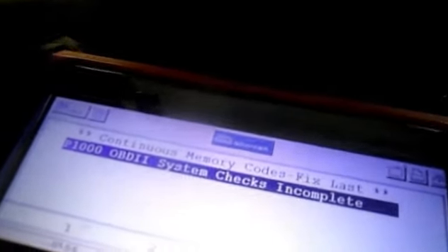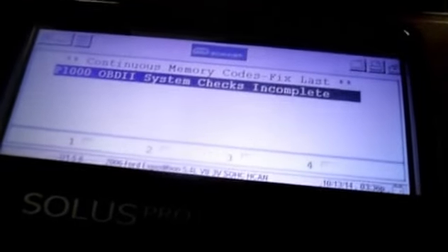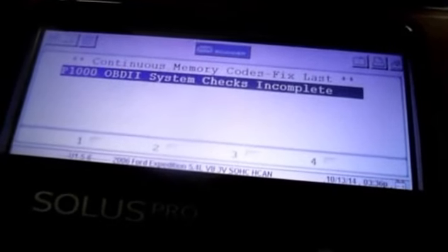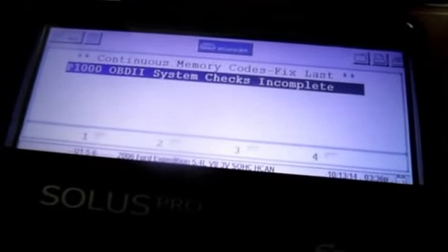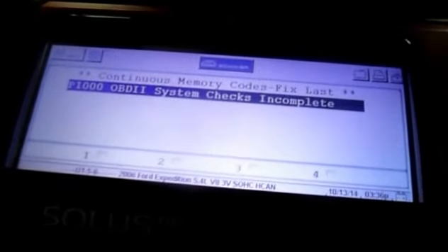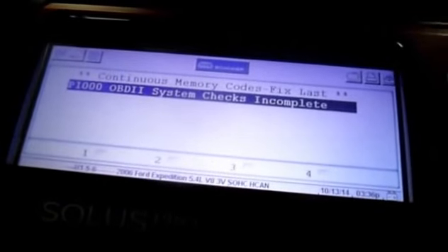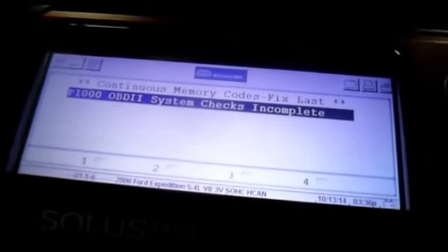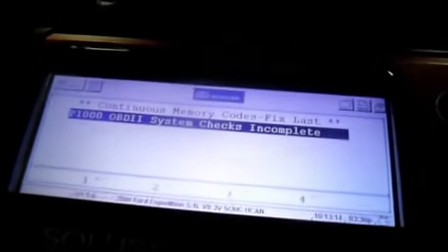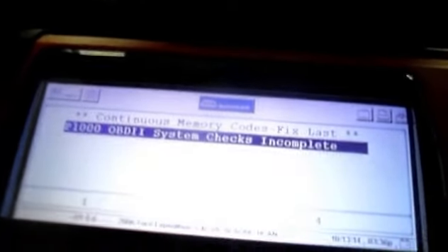The next thing we're going to do is go down underneath by the transmission, disconnect the sensor, and check the resistance. From what I recall, a good sensor's resistance should be anywhere from about 400 to 700 ohms or something like that. So I'm going to check it on the computer, and we'll get down there and check it. Let me grab some tools and we'll come right back.